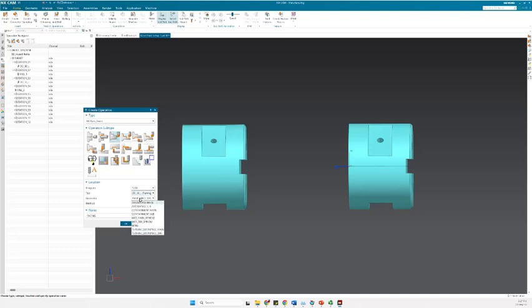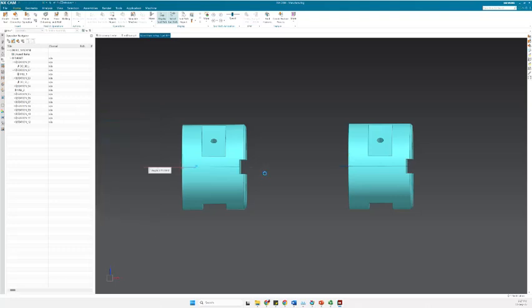The geometry is something important to take into account. Containment main, because we are on the main spindle, so we are going to manufacture the left side component first, and the method to be chosen is the lathe rough. So for example, we can just call this one facing and so on.